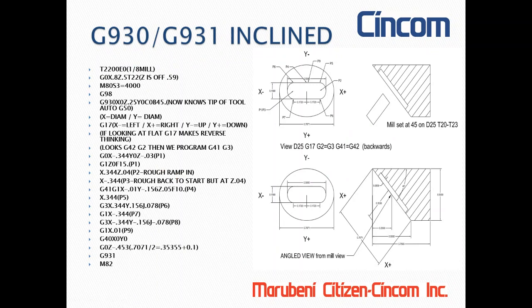Canceling offset will not be allowed over the inclined surface machining. You can change it, but you have to cancel and turn it back on again. Also, if you have to change the offset, you cannot use absolute designation like X, Z or Y. It has to be as U, W, as incremental, and then you have to turn the inclined surface machining back on again.